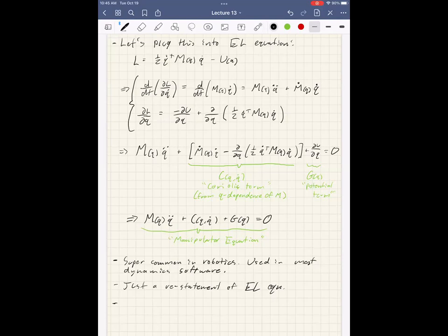Yeah, so there's a few variations that you'll see of this. One is what you just said, where you factor out a q dot. There are some quirks to that. If you do that, it's totally fine, but the definition of the C matrix becomes ambiguous. It's actually not clear, because there are multiple q dots floating around in there.